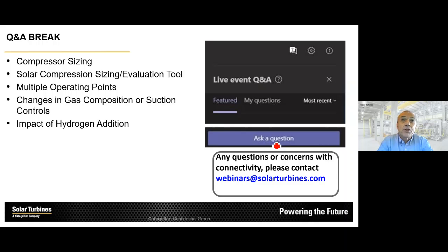And on some machines, you will get to the point where even if I open that discharge throttle wider and wider, the pressure will drop, but the flow will no longer increase. That is the classical choke or stonewall situation. That also typically comes with a significant reduction in efficiency. It depends on the design of the compressor whether the manufacturer puts in limitations on how far into the high flow region you can go. We typically don't limit that with our machines though. But the short answer: choke, stonewall, overload, it all refers to operating conditions at very high flow and very low head.